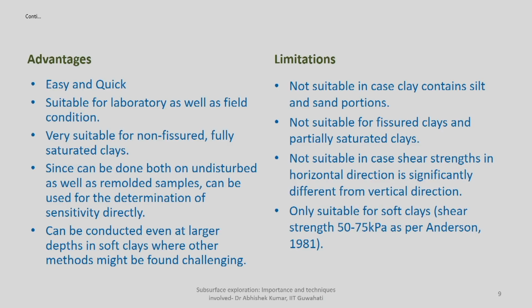advantages and disadvantages. Advantages are, it is easy and very quick: you simply lower the torque vane, start measuring it, then bring it onto the surface. Whenever you are interested in determining the shear strength, you proceed to that depth maybe by boring, then remove the boring setup, put in this vane setup, and measure the rotation, followed by the shear strength determination. So, it is very quick and very easy, so chances of error are very less.